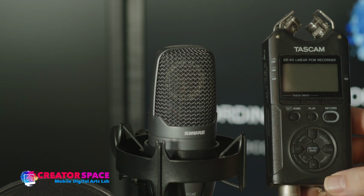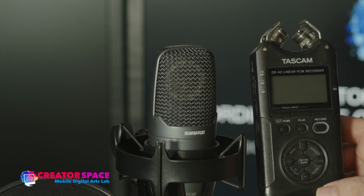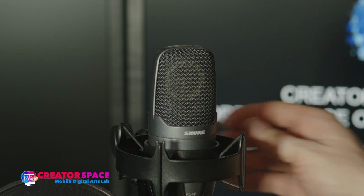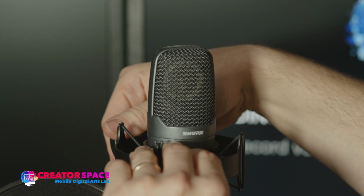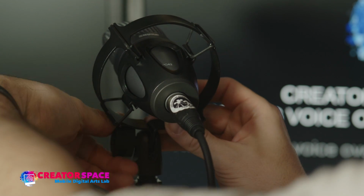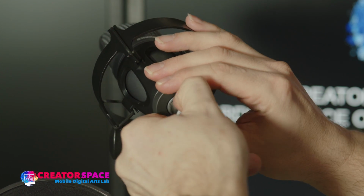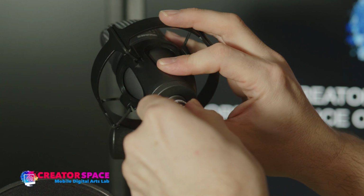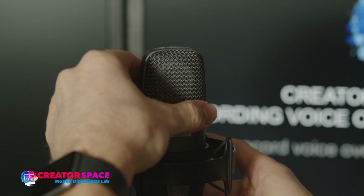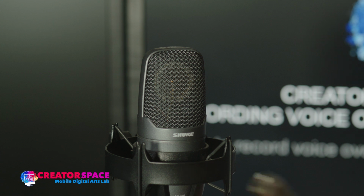But overall, for voiceover and podcast recording, I find you'll have the best quality with these condenser microphones. You simply set them up; they're XLR based, and they also require phantom power. Phantom power is the use of 48 volt power that runs through the recorder to the microphone to power it. You put the XLR cable right into the bottom here. Okay, I'm just going to tighten that up, and that's attached. Now the other end is going to go into our sound recorder.